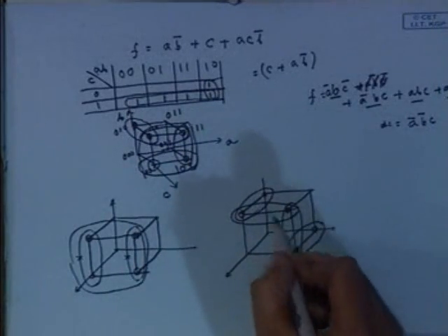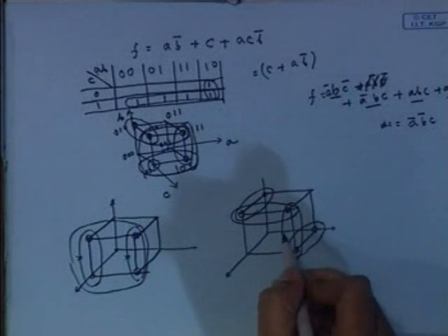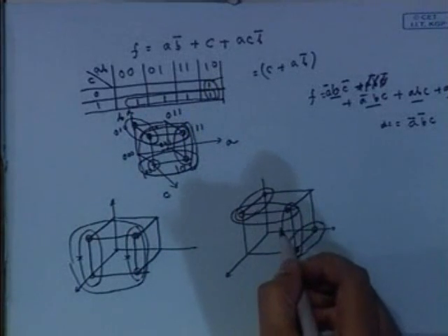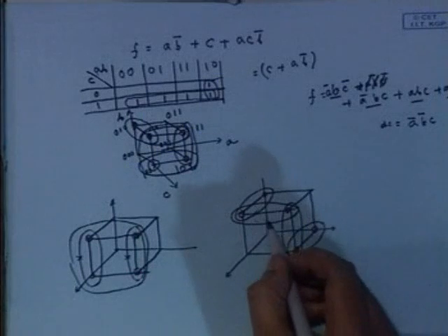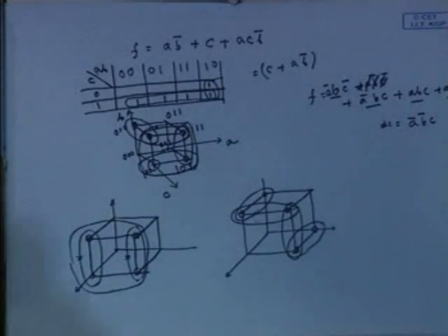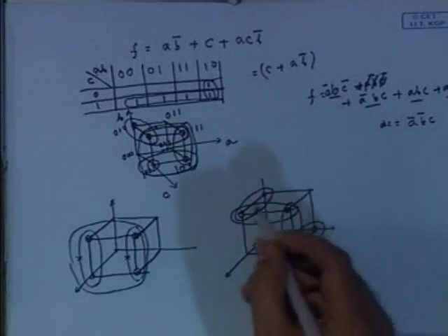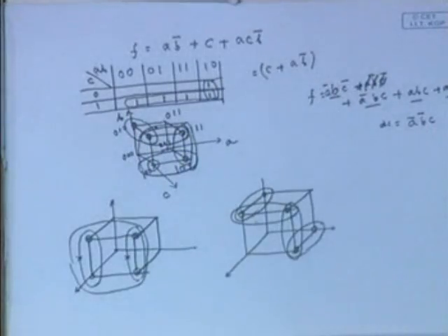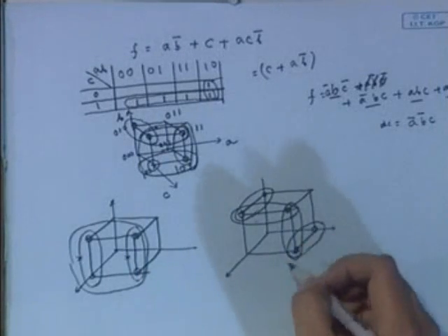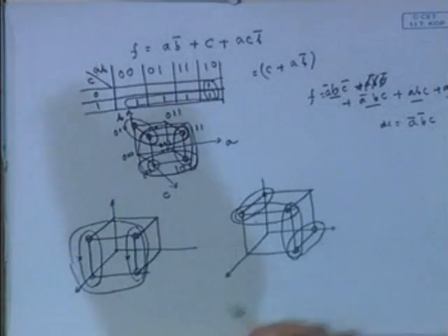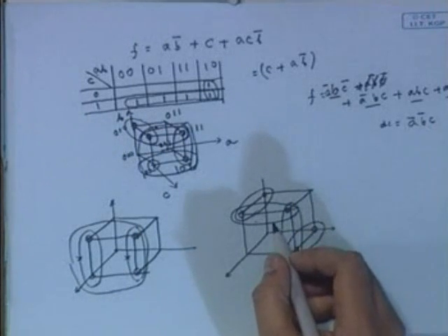Now after expanding, you see that these two cubes are not required at the same time. One of them will suffice. Suppose if you remove this, you will also cover all the min terms, or maybe you can remove this. This is the irredundant state. You will remove the redundant cubes.